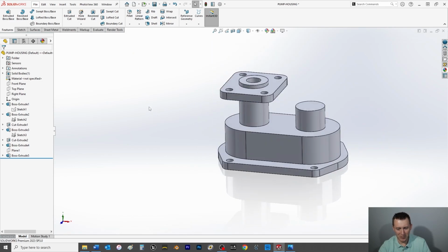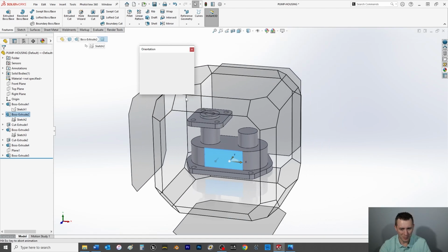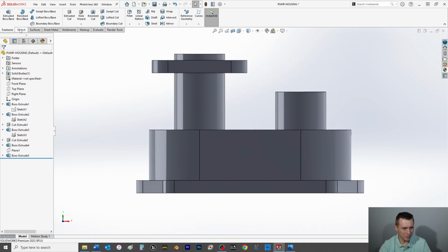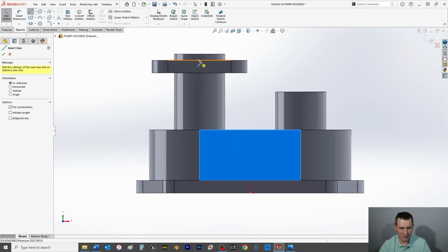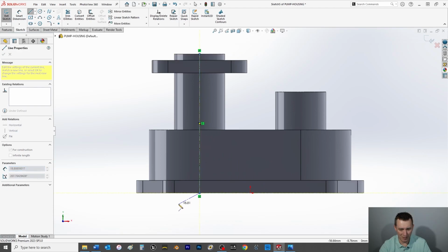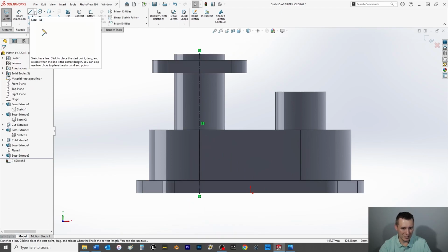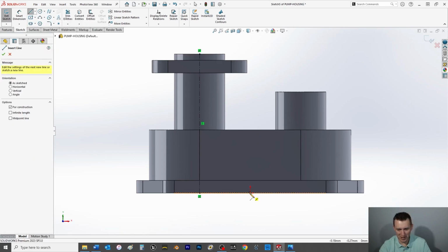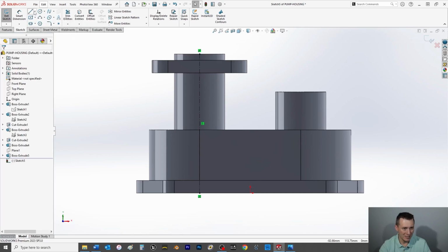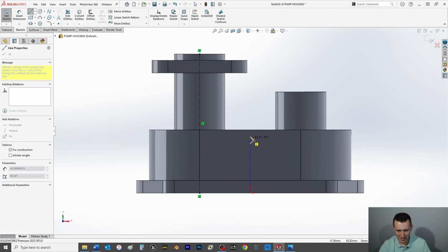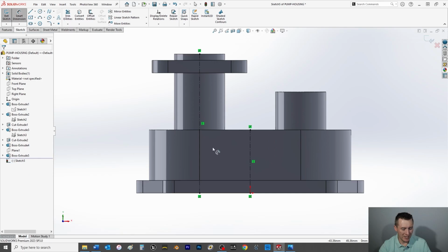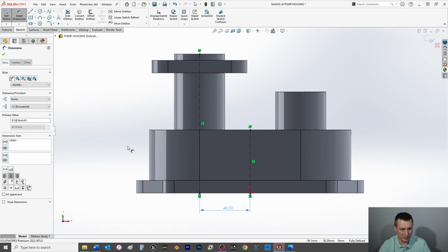Now we just have to go in and finally make one more thing. So we're going to click, we're going to make the Mario pipes, and we're going to end this in a special way. So select that face, normal to. Select the face, do a sketch. Now here's what we're going to do, kind of a sanity reference. In the drawing itself, it shows this line as a reference. Now watch this. This is going to be crazy because it's technically still the center. So we'll choose two center lines. And again, these are both fully defined, so this dimension is just purely for sanity and reference sake.